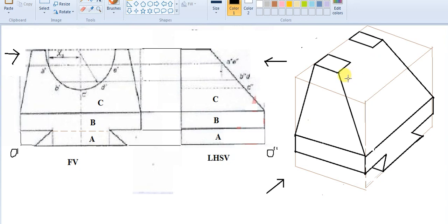in today's session. Now it is quite understood that the circle that we can see from front is present on this particular inclined surface, and in reality it's no more a circle, it becomes an ellipse. But at the back end, which is a straight surface, we can see that as a circle of the equal radius. So let me try to draw the schematic of it.